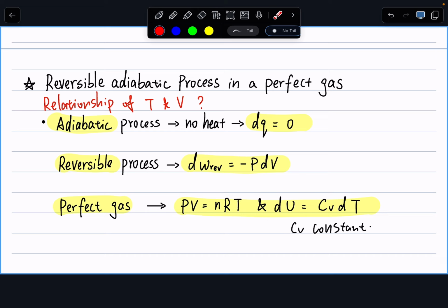Like the example question we did, remember we talked about the specific heat of a piece of metal. You drop it into the water and measure the specific heat at that initial temperature. You can do that experiment multiple times to get a curve of Cv versus temperature. So Cv is typically not a constant. It is only a constant for ideal gases. Okay, any other questions?